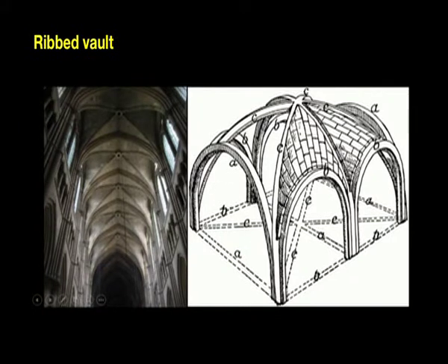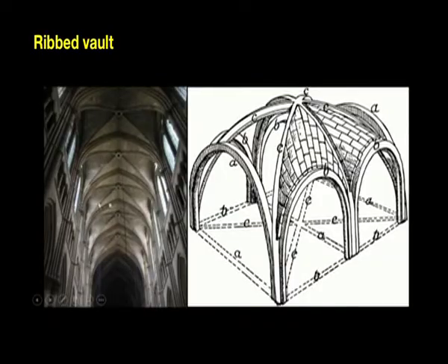Here you go, these A, C, B, these are called ribs. Wherever you have an intersection of these arches, you have something called ribs. It is called a six-partite vaulting because there are 6 ribs which meet in a particular unit of a vaulting system. Let us take an example of this particular system, where you see 1, 2, 3 ribs arising from this side and 3 ribs arising from this side. In this unit, there are totally 6 ribs. So, this is called a six-partite vaulting system.